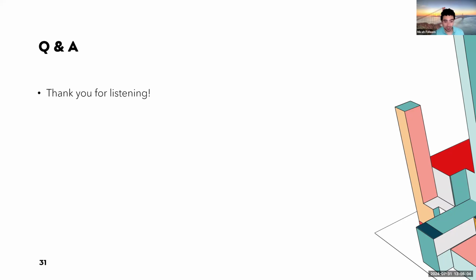There are many software packages that work on top of Geant4. Yes, those are great. GATE is another one for medical, a pretty popular example. Yeah, Geant4 is a great base to start with. And if you have a more specific application, like you want to do PET, and you know that you're going to be simulating these geometries, detectors in a ring around an object, and you're working in that space, you want to create a lot of facilities to make defining those geometries really easy, which Geant4 doesn't have. You would define those from scratch normally. So GATE has facilities for, say, I want a PET system, and it's got this inner size, and the detectors look like this, and then it just places them all for you. So those are fantastic. Those will save you a lot of time.